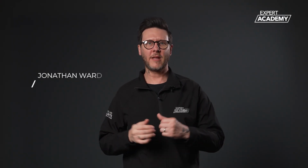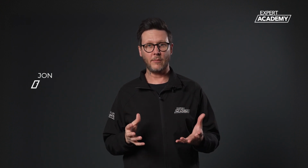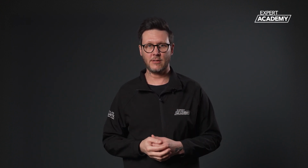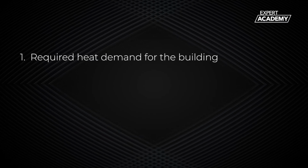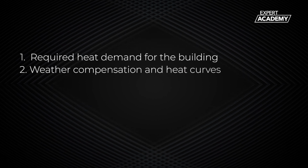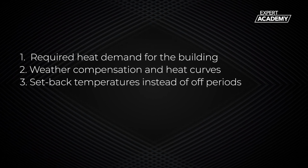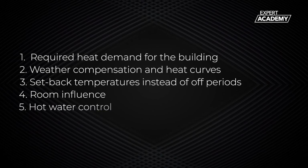Let's look at control methods for a heat pump. There is more than one way to control a heat pump, but we will cover the best practice methods to ensure good levels of efficiency. Key points that we will cover are required heat demand for the building, weather compensation and heat curves, setback temperatures instead of off periods, room influence, and hot water control.